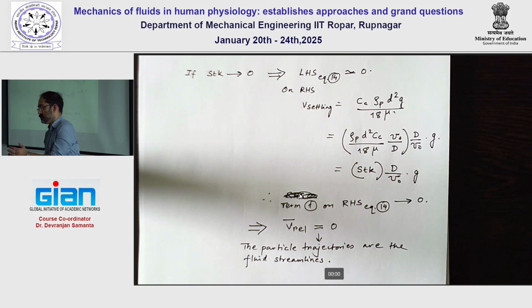If it is even a 2 micron particle or a 1 micron particle, because of that small d, there is always that huge impact on the Stokes number getting much smaller. Now whether the rho p being 1100 kg per cubic meter rather than 1000 kg per cubic meter is enough to balance that effect is a good question. The considerations that you showed are the typical ones, where it won't be that much of a difference.